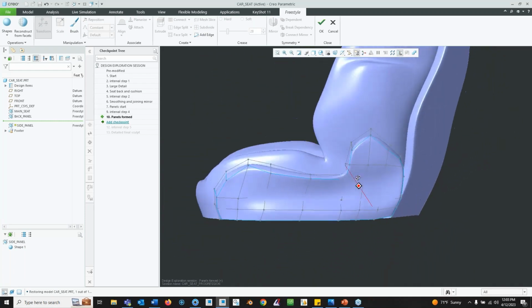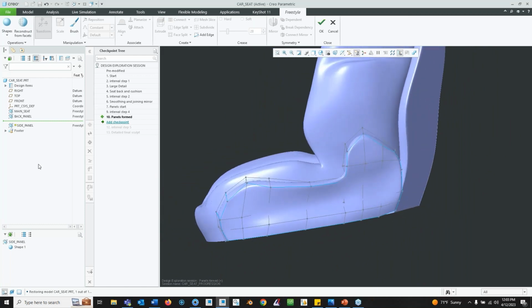But if I'm happy with the overall shape, I could subdivide it, and then as you're getting higher tessellation, instead of adding one edge at a time, you'd be looking into pushing and pulling groups of faces and groups of edges or vertices. So we cancel out on that.